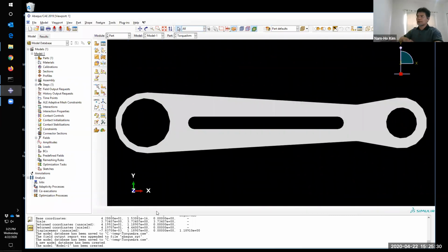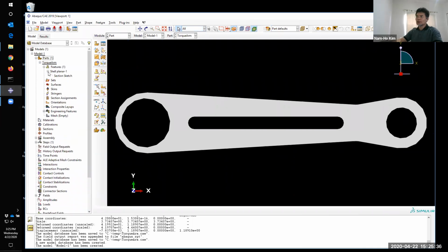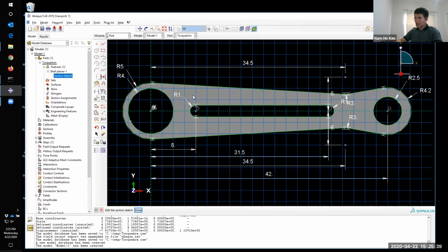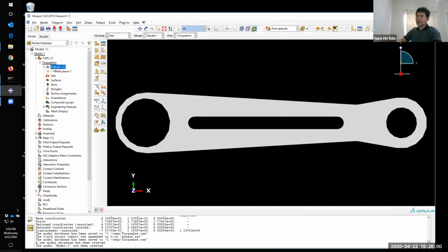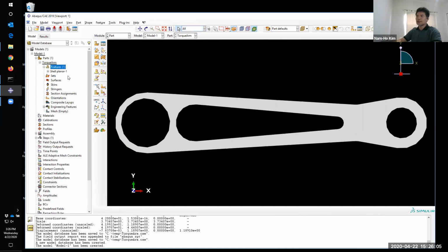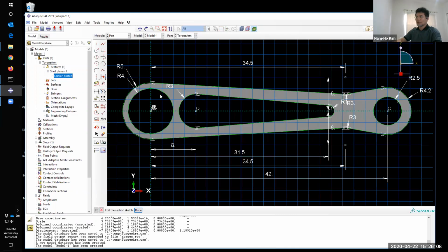All right. So we are done. So this is your initial geometry. When you want to change it, you can go back to sketch. The gray area is what the solid looks like, and the greens are your current boundary. If you change any of those, like this, and then you finish the sketch, I want to increase the radius to 3. Nothing has changed because you did not regenerate it. So you need to right click, choose the option regenerate, then it will regenerate the model. Go back, change back to 1.